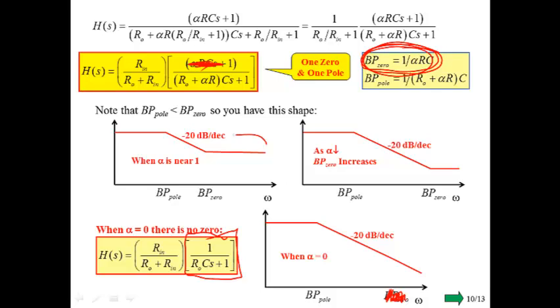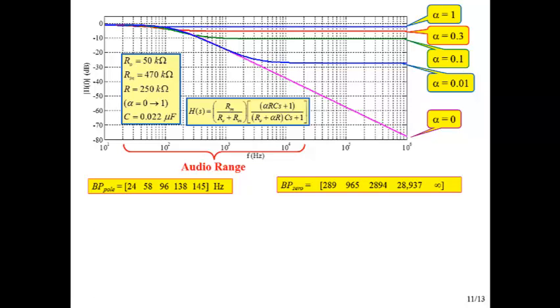So noticing that we've got things that behave like this tells us that we would not be able to simulate this circuit using the impulse invariance method. We'll have to use the bilinear transform to simulate this thing. So if we do a nice freqs plot of this, we can see for different values of alpha what happens. So when alpha is equal to 1, we hardly have any degradation of the high frequencies at all, maybe a tiny little bit.